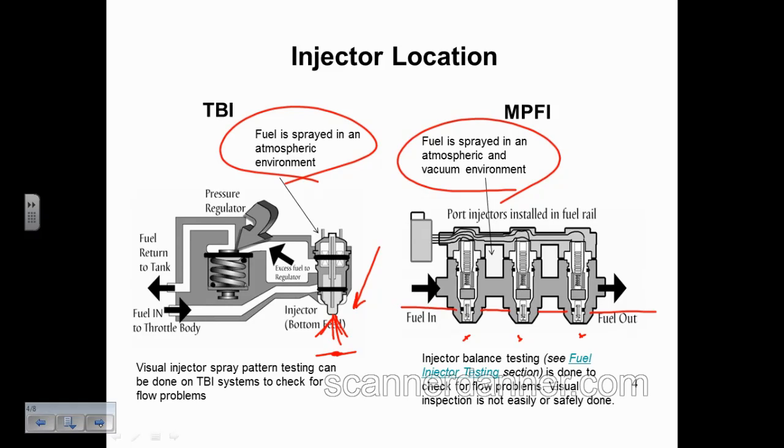It wasn't for power. A lot of people think that the vacuum hose on top of the regulator is there to produce higher pressure at wide open throttle because we need more fuel. And that's a common misconception. It has to do with this effect down here, and we'll get to that as we continue.